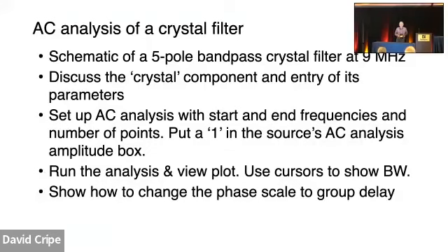Okay. Now, another AC analysis, this one I said this thing is so useful for, and it really is, and very accurate too. Now look at a crystal filter. I have a 5-pole crystal filter at 9 megahertz. I want to talk about the crystal component. It gives you a graphic symbol for it, but as far as LTspice is concerned, it's just another capacitor.